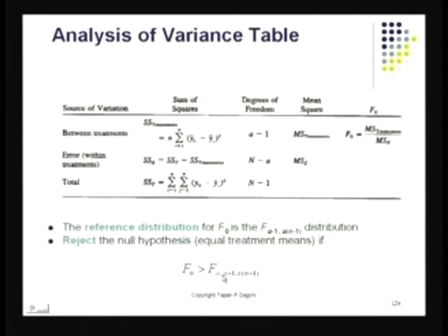And if it is greater than the critical value, I'll be rejecting the hypothesis that mu1 equals mu2 equals mu3 equals mu4 equals mu a. This hypothesis I'll be rejecting. In fact, what I'll be saying is that changing RF power did in fact impact the response, which is etching. So changing RF power, this is initially what we started out to do.